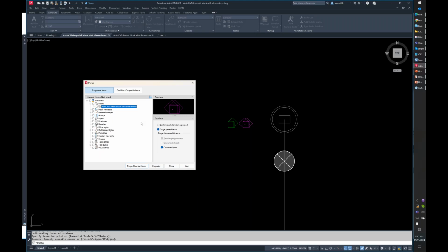As with my other question, the blocks palette also slows down my AutoCAD restart. So that may depend on where your library is pointing to, Tim. That could be your block MRU, or your most recently used, which is generally out of the box 50. We may need to set that back to 0 and then see if it's any faster. It could also be a configuration issue. We would probably need to look at that from a more technical standpoint to see.